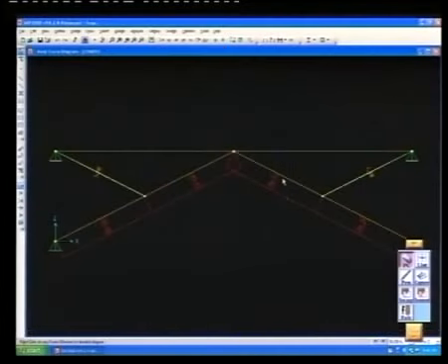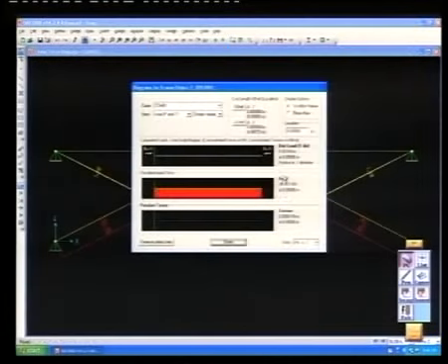you will find that the force in the member is what? It is not apparent. Okay. Look at it. 85 kilonewton. Its capacity is 22 kilonewton, and the ultimate load is 85 kilonewton. This will lead to collapse.